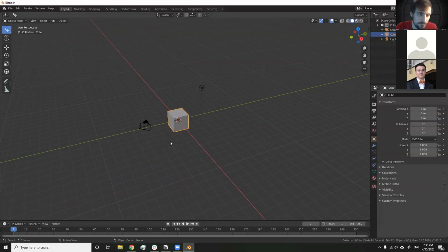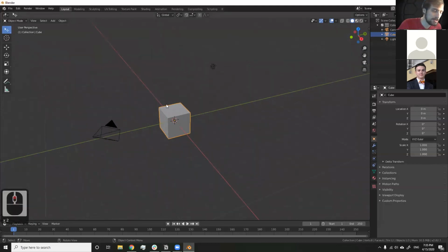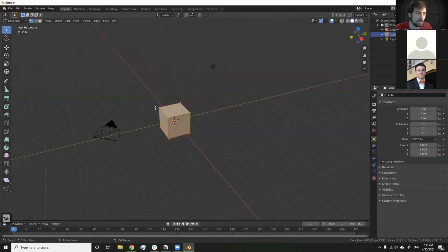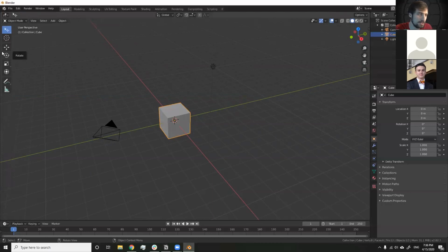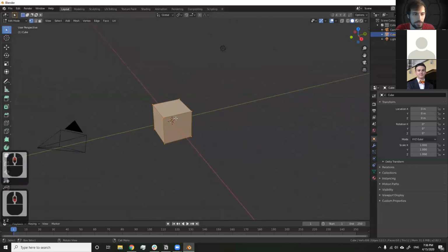All right. So we're going to go into some editing tools. Your bulk of your changes in Blender will be in the edit mode. So to do that, you select your model that you want to edit, and then you hit Tab, and that will bring you into the edit workspace. And you'll notice that on the side here, you have these basic controls. So for example, you have your move, rotate, scaling tools. If you hit Tab, this toolbar expands and brings out a bunch more tools, and you see your view kind of changes as well.